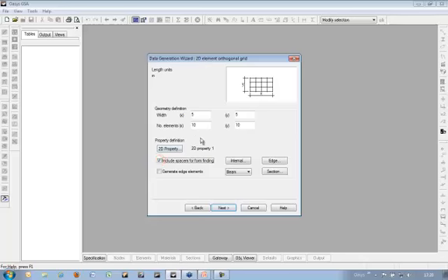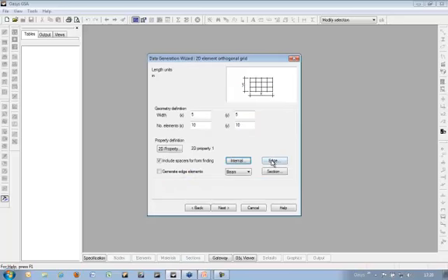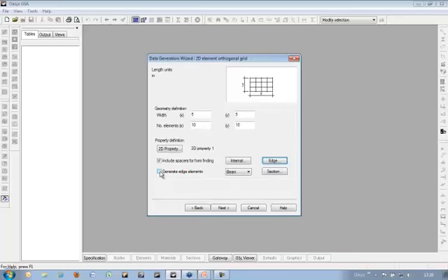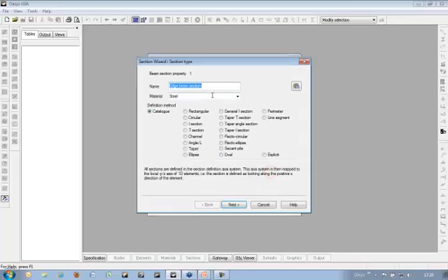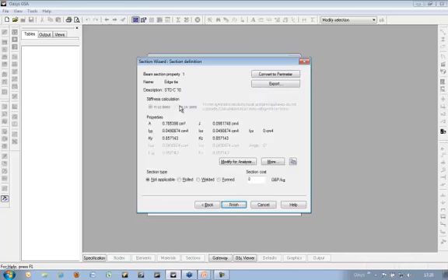I'll need to include spacers for form finding. We've got the internal spacers, these are geodesic, so these spacers will ensure that nodes remain on the surface of the fabric, whereas the edge elements are free to move around as they feel necessary. I'll have edge elements which I'll put in as ties, and the edge will be the edge tie, and we'll use a 10mm cable for this.